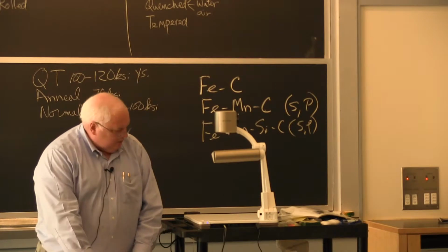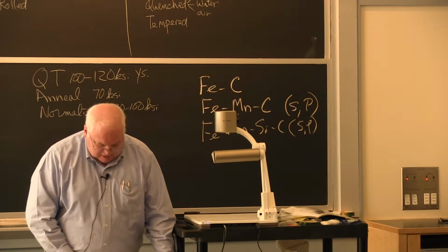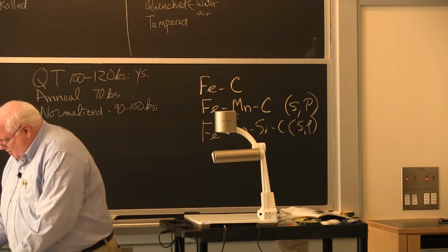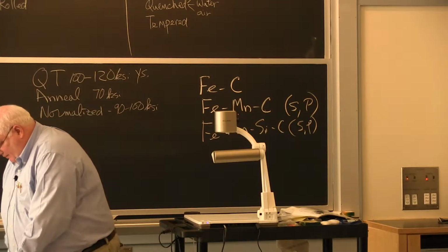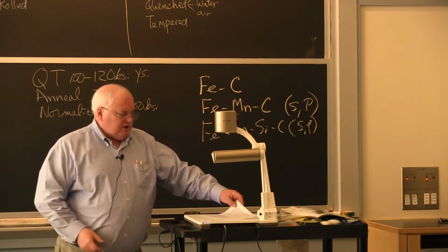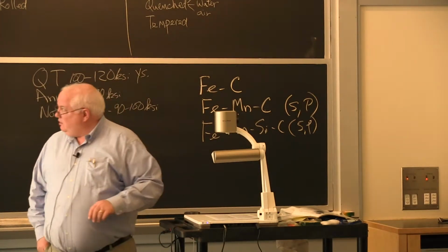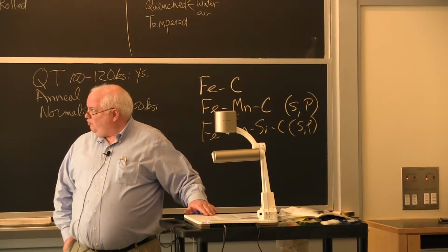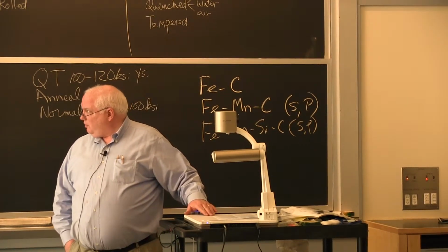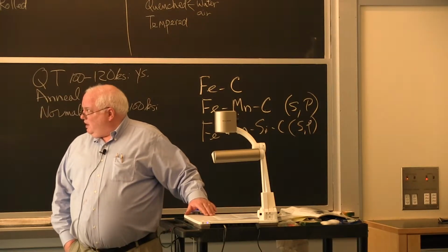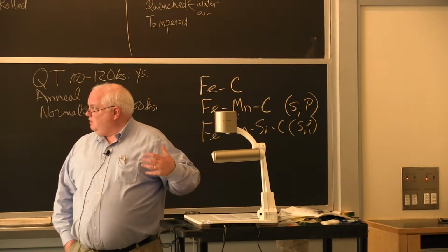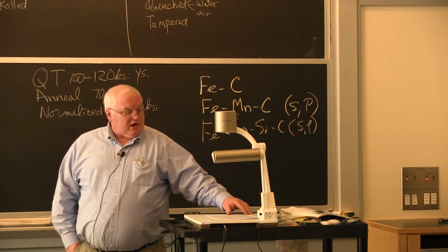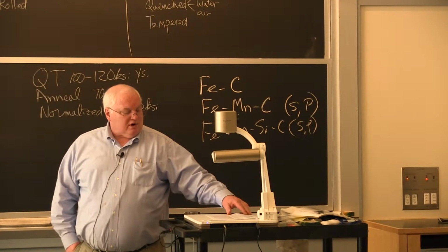Okay, if I go back to some of these phase diagrams, again, or not phase diagrams, transformation diagrams, we talked about hardenability and hardening. Hardenability is the relative ability of a ferrous alloy to form martensite when quenched above the upper critical temperature. And in fact, we want to know the hardenability in terms of the thickness of the steel that can be heat treated to a given hardness.